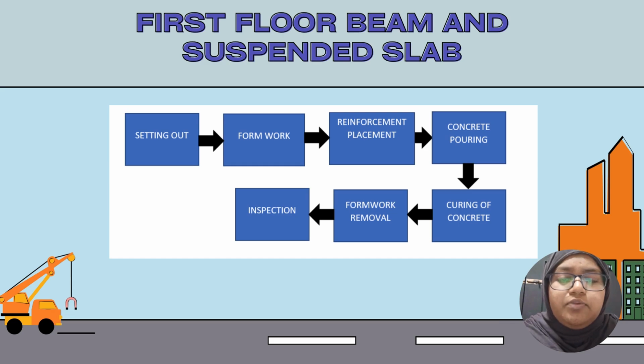After we finish the concrete, and when the concrete is half hardened, we can do the next process, which is formwork removal. We need to loosen the formwork carefully to avoid damage to the beam and the slab.